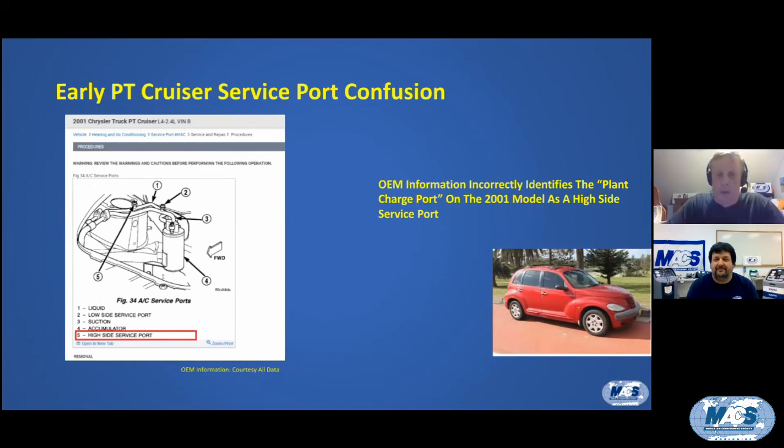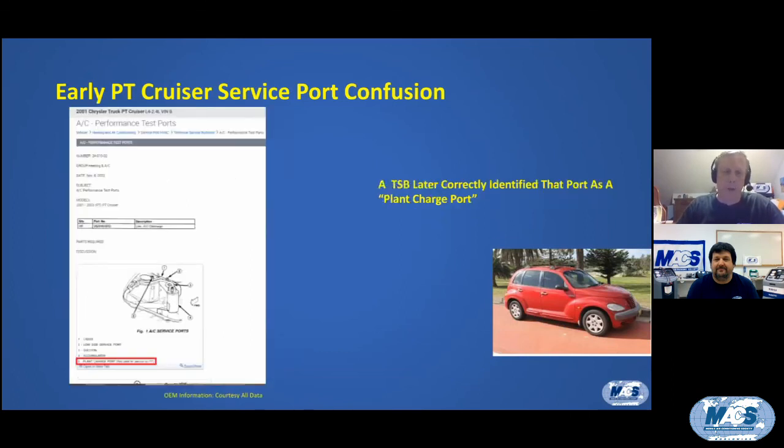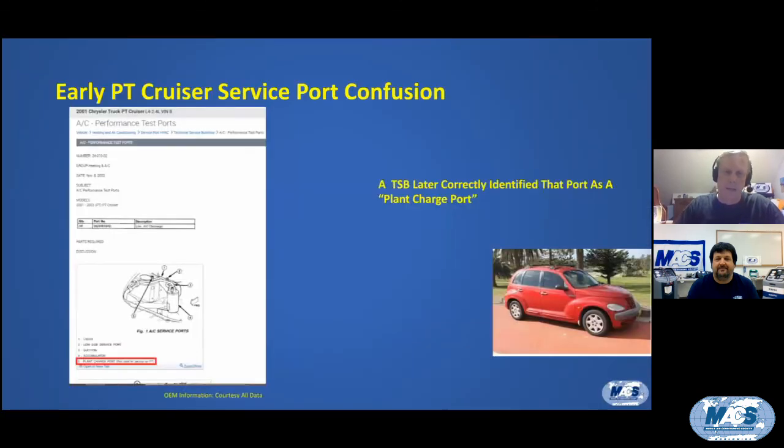And that was corrected later on in a TSB. There was a TSB that came out that addressed it, that stated that that was the charge port, and that the true high side service port was located down on the discharge line. I thought I had a slide that actually showed that, but yeah, they corrected that in that TSB. But there's still a lot of guys that connect up to that charge port, and it creates a lot of confusion as a result.